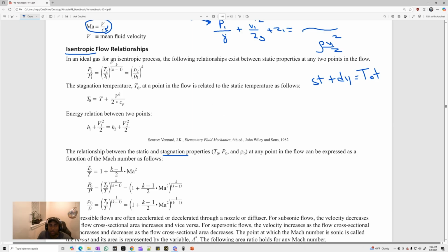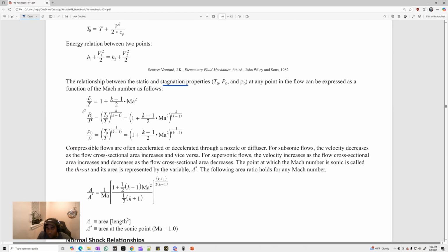There's something special about isentropic flow: the total properties remain constant throughout the flow. Like the pressures that we were given, the total pressure remains the same. We don't know what the total pressure is, but at state point 1 we know the Mach number and the static pressure. We can use these two things to give us the total, or stagnation, pressure at state point 1.